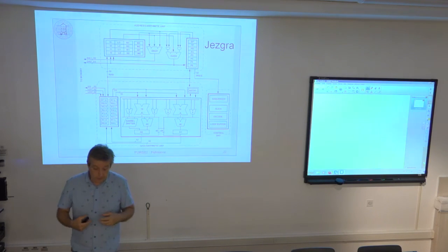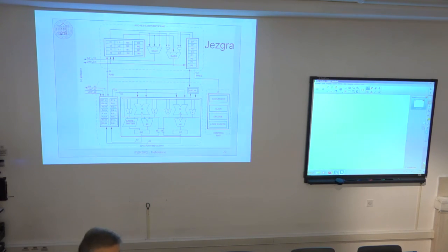Now this is useful for image processing applications, because in images, the pixel values are typically represented with bytes, with 8 bits. It is sufficient to represent the grayscale level or the value of red, green, and blue. It is sufficient to have 8-bit values for these intensities of red, green, and blue. Now if I want to add 2 images, then I have to add these 8-bit values.